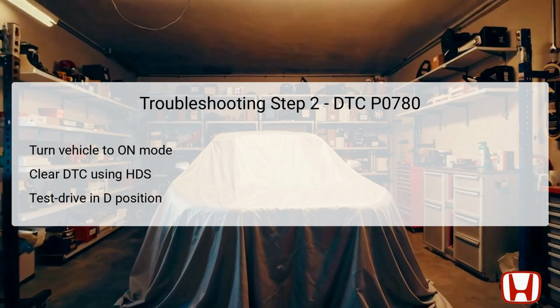After reaching the required speed, slow down and stop. Then accelerate again from a standstill at full throttle. This sequence simulates various driving situations that can affect the transmission's performance. Turning off the engine and repeating the test will confirm whether the issue is resolved or if further diagnostics are needed.